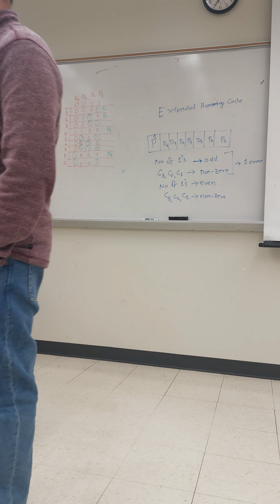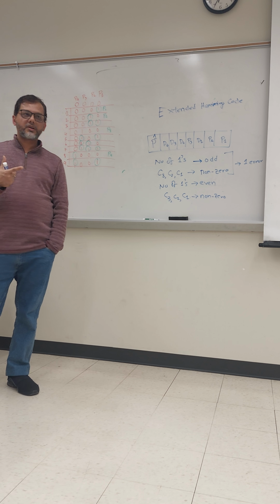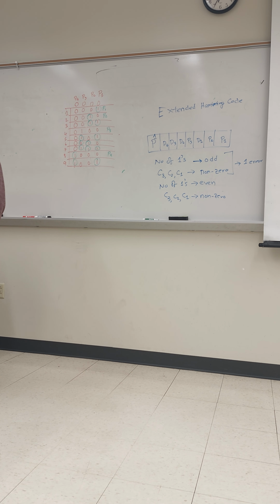To identify logic high, that means 5 volt or 2 volt or 3 volt, as I mentioned, is a logic high, or logic low, 0 and 1. Logic low is from 0 to around 0.8 volt, we decide, right? So in logic gates, we have the three basic gates: AND, OR, and NOT. Then we have two universal gates, the NAND gate and the NOR gate. By using NAND and NOR, we can implement any kind of Boolean expression.